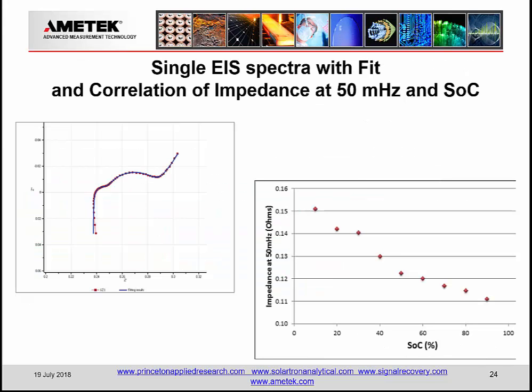And that's what I've done here with products from our MODULAB platform, doing single sine impedance at 50 millihertz, so a fairly low frequency, and we can watch the state of charge change, not just at the total sweep, just running impedance at that low frequency. And that's really how these things work, right? You are basically going to sweep the frequency until you find a characteristic frequency where these changes happen, and you're going to build a sensor, and you're going to investigate that frequency over and over and over, and tie that directly to state of charge.